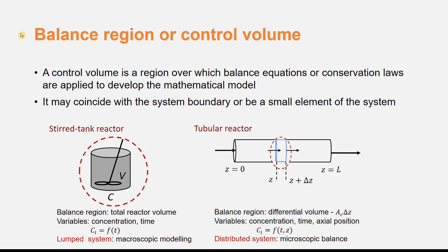The balance region, or control volume, is a volume in space over which the balance equations and conservation laws will be applied to derive the mathematical model. The control volume could be the whole system if the system is considered perfectly mixed, as you might do for a batch reactor or CSTR.